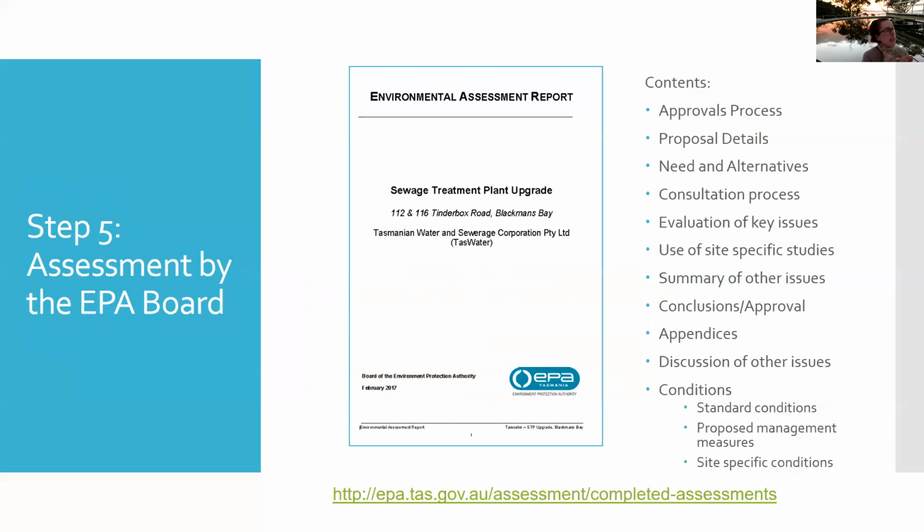And I think what we ended up doing in the end was, there are little ports on the pipe that goes out. There are these little ports about where the kelp forest is, and then there's a big port at the end where most of it comes out. What we worked out is, we could try and get a little bit more effluent going out through those ports, because it was higher treated and they need a little bit more effluent to support them. So if there's a will, there's a way. And engineers always have a solution, I have found.